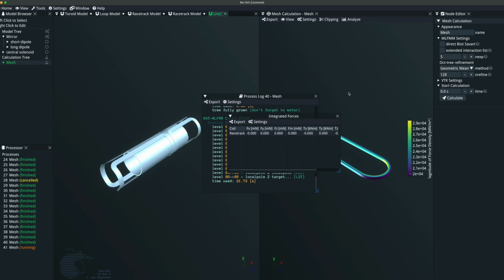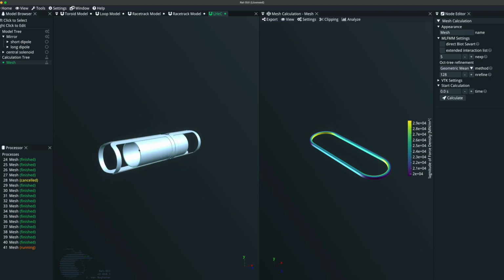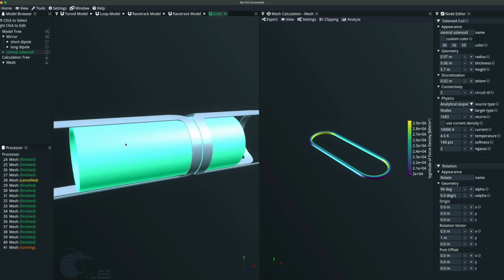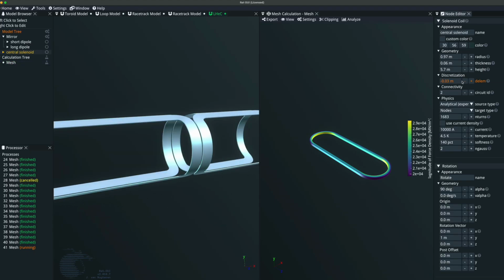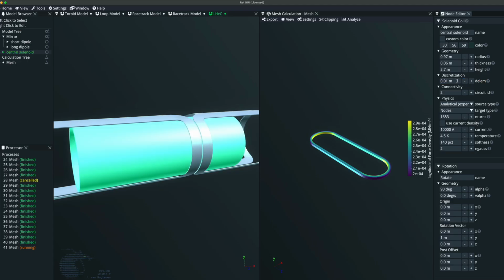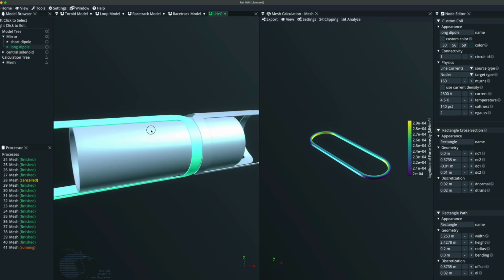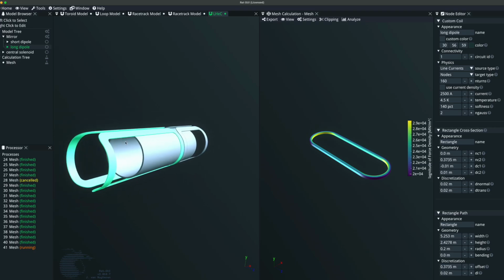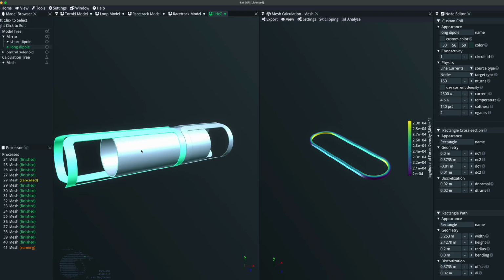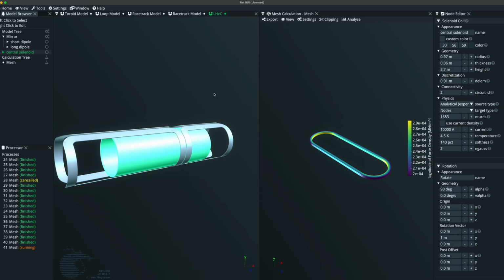So you can play with the settings, right? That's why it's a coil setting, it's not a calculation setting. For where you need your accuracy, you can increase the element, or decrease the element size, because that makes it also more accurate. You can set it to analytical, but for these, since you are not interested in the peak field there, well, eventually you are, but the peak field is really on the solenoid, you can make your calculation faster by playing with different settings for different coils. And only when you go and look at the forces, you can go to Gauss points. That's really it. One last thing.